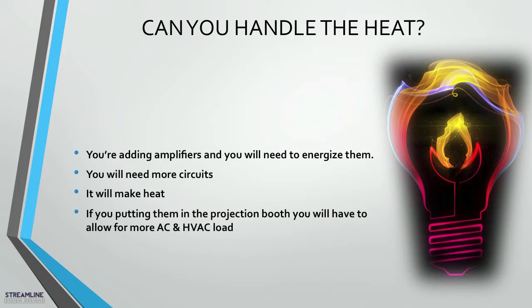Handle the heat. You're going to be adding amplifiers, and it's going to get warm. Do you need more circuits? Yes, you do. You might have to do panel upgrades, which sometimes will happen, and you won't realize that cost is going to be there unless you do the load calcs and start looking at these other things around you. Yes, you want this big sound system, but you have to look around and ask whether this venue can do that. And obviously you're putting in the projection booth, so you're going to need more AC and more cooling.